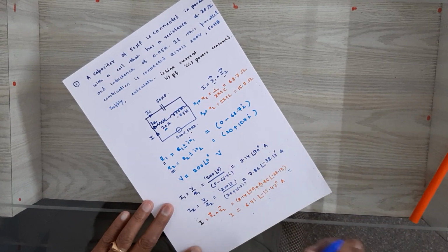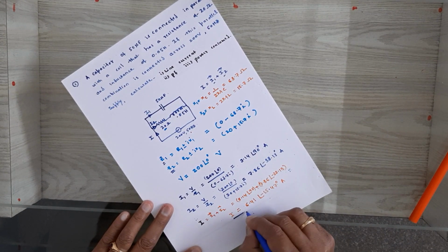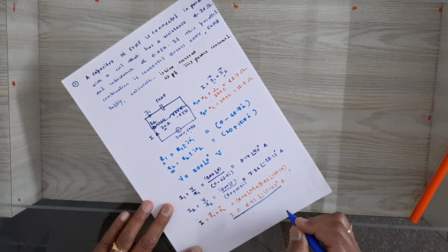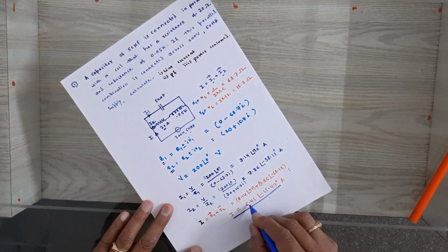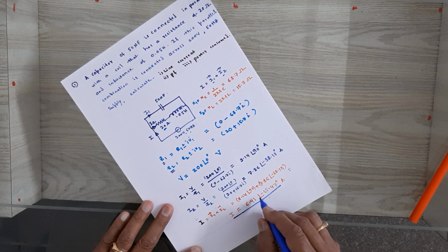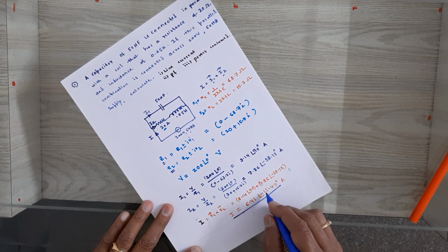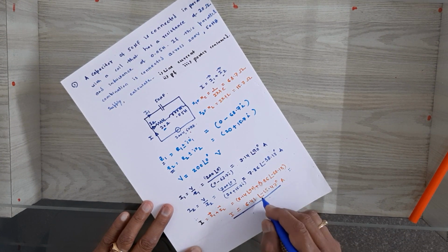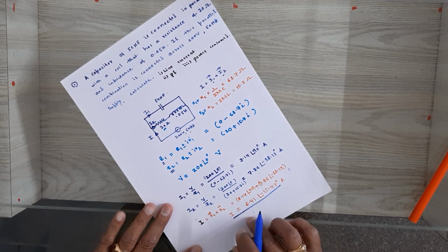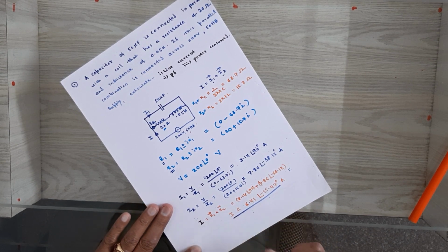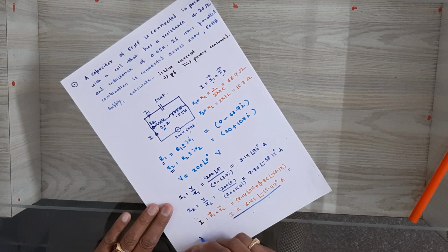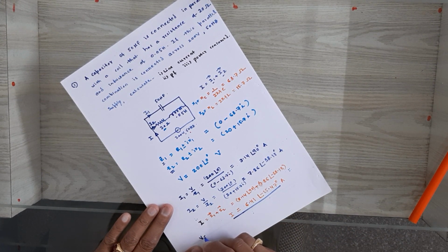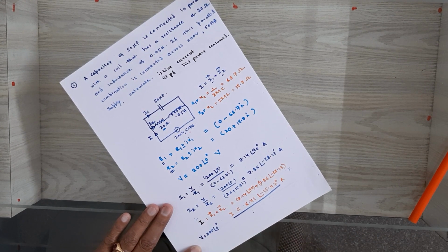You are getting the current I, the total current I. You ask the line current. The line current is 6.4 amperes with an angle of minus 15.47 degree with respect to reference. Then how to draw the vector diagram for this? This is a current. What is our voltage? Voltage V is equal to 200 and angle of 0 degree.